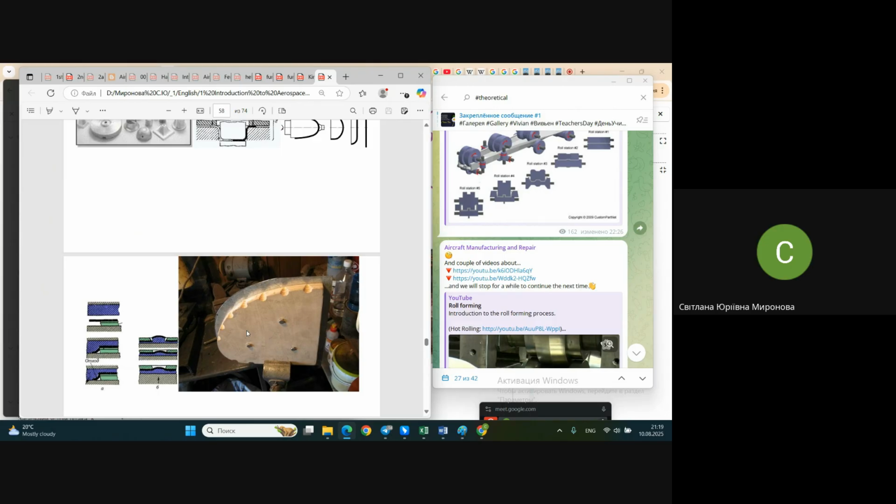Do remember this, that for forming, flanging, it's possible to release one of the tool, half of the tool. It's possible to work only with the punch without die block. Instead of die block, it will be a universal block with polyurethane, placed in a container, and due to this you save money.